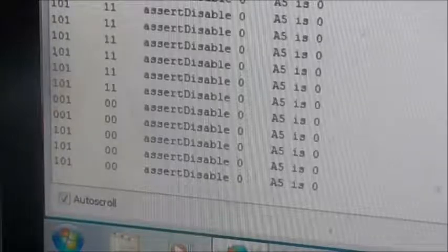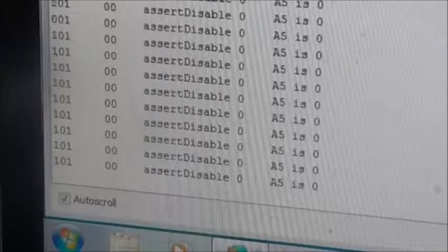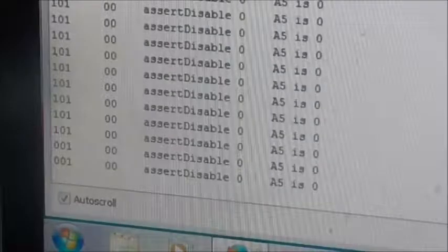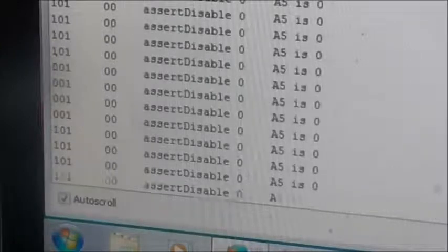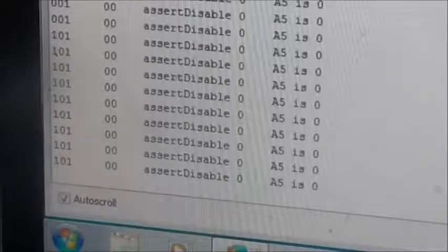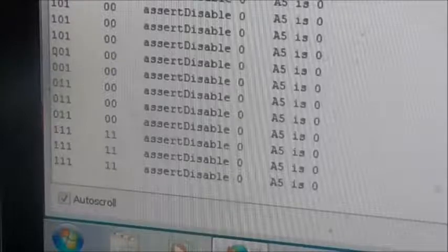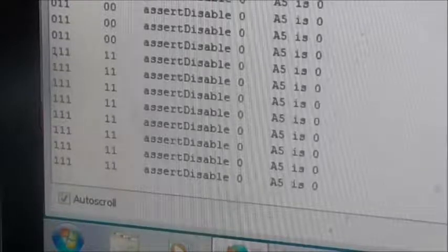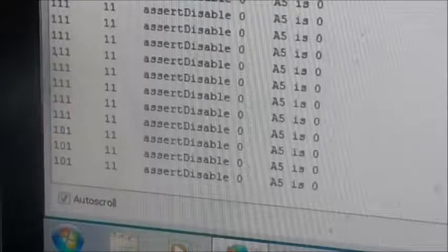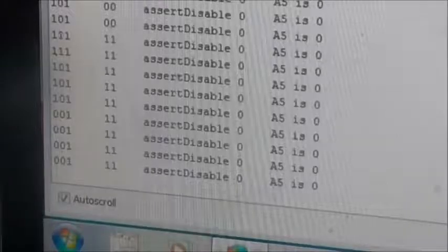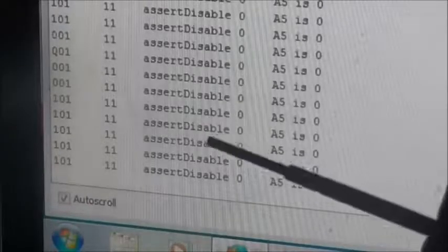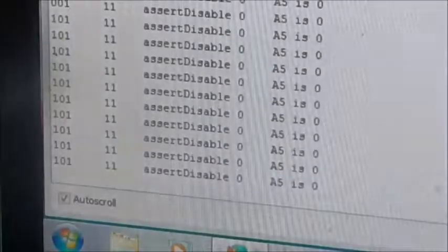Over here we're measuring the outputs, and I'm going to remove the siren so that we won't be disturbed by it while we're talking. So let's set the PIR sensor off, undo the window catch and stand on the pressure mat. And there we are. You'll see that the next column along goes to 1, 1, and that of course is the outputs of the Arduino. Now looking at some more output, you'll see that the inputs stay high regardless of what the output does.